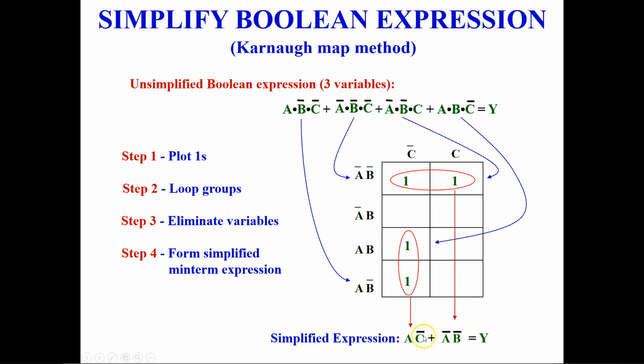We simplified this from the truth table also, and now we used another method, which is the K-map method. You might be thinking, why do we need the K-map if we can use just one method? My answer would be that right now you're dealing with just 3 variables. Just imagine if you have 4 variables or more.